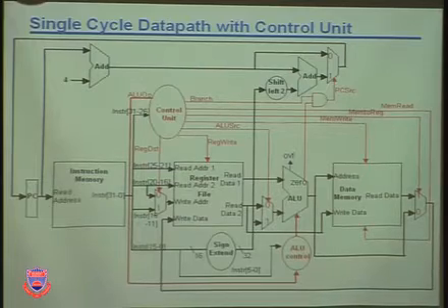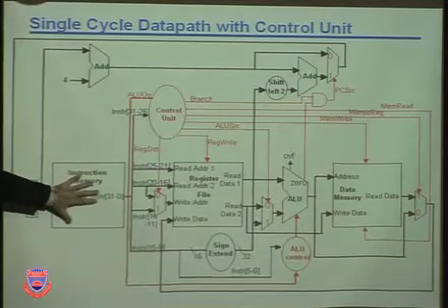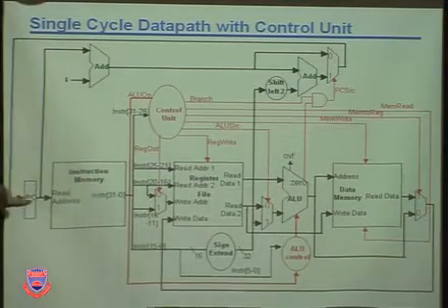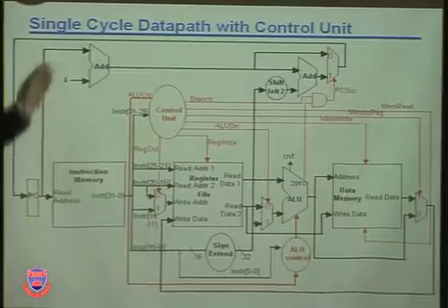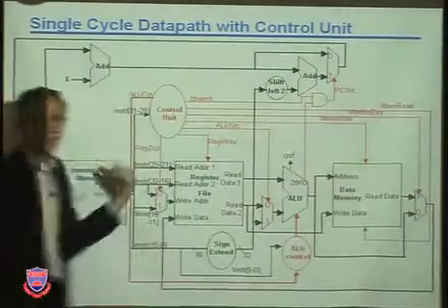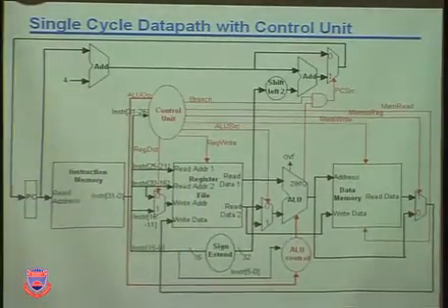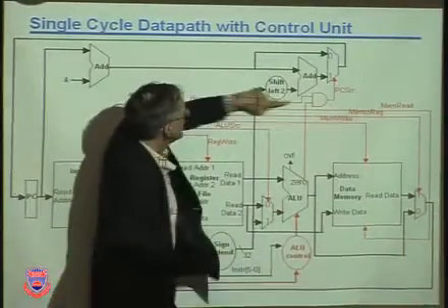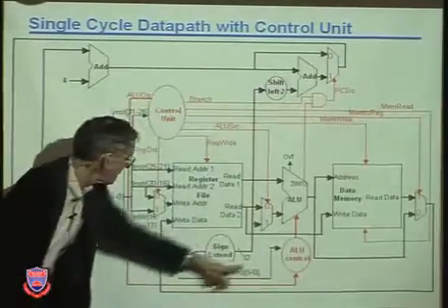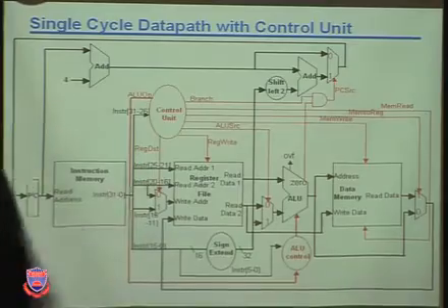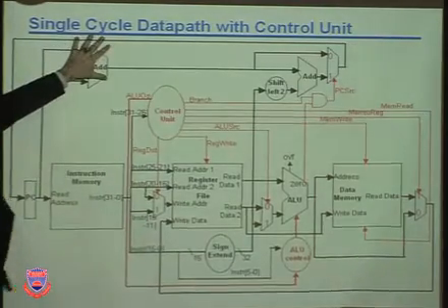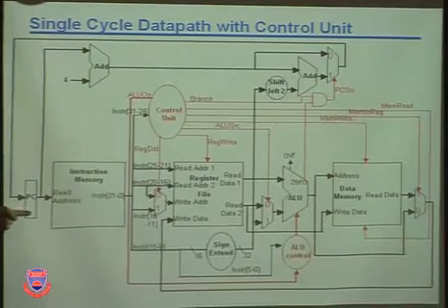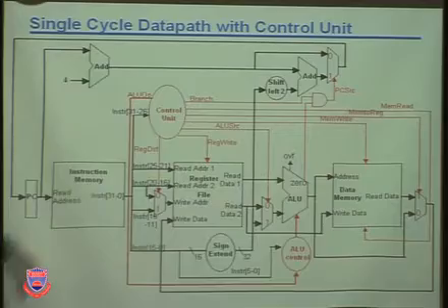Branching stuff, right? It's obviously branching stuff. Here's our instruction memory. The PC is here for fetching, but it's also for computing the next PC. That allows us to either add 4 and take it, or add 4 and then add something else, which comes from the sign-extended immediate. So that's our branching: computing the next address and writing it into the PC. We don't have jumping up there yet.